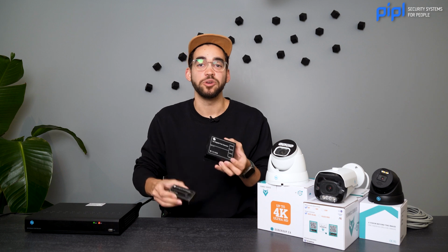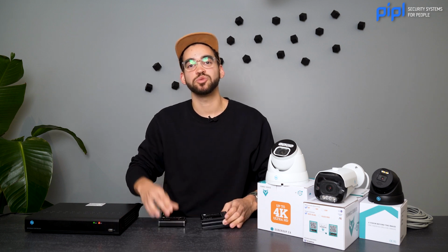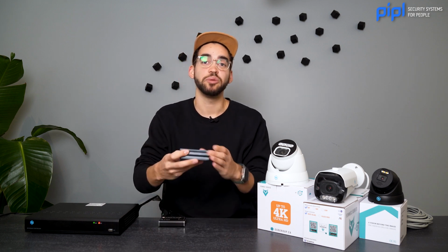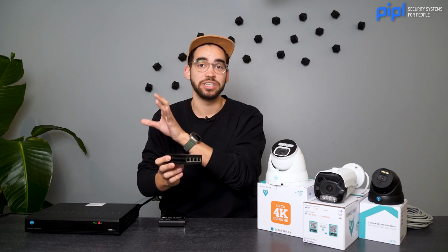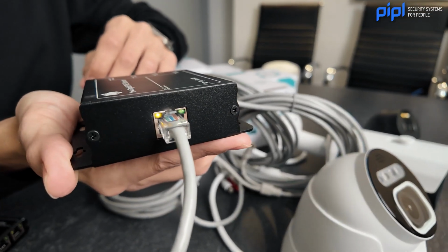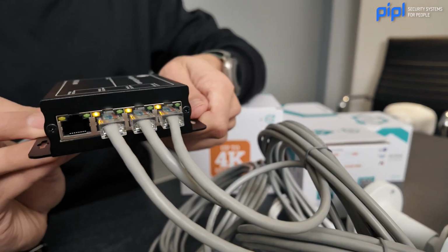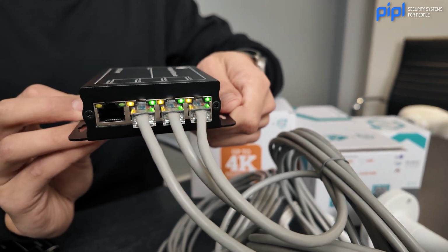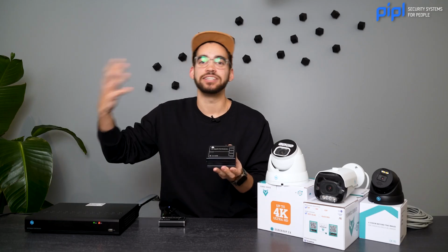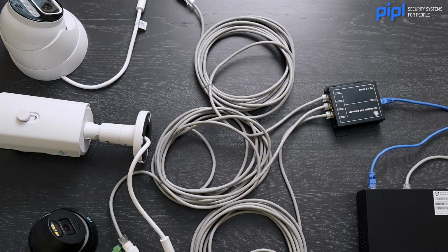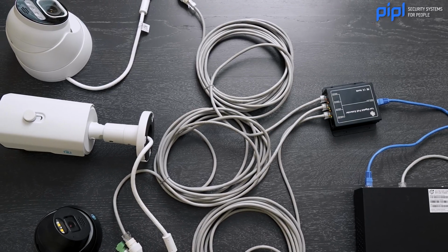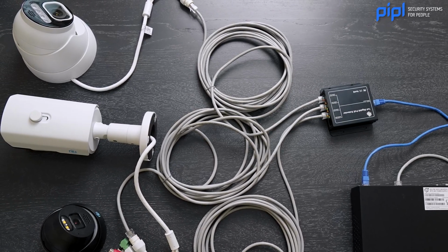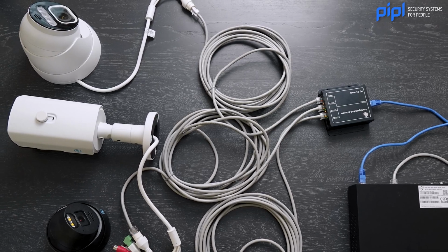extenders. So the way it works is that PoE extenders will help you do the connection from an installation that you already have. So let's say we take the Cat5 cable from the IP camera, we put it in the input of the PoE extender, and then we can connect 4 more equipment through it. So again, facilitate the installation all around. You don't need a PoE switch. So it's really good if you don't have any kind of power outlets near your installation.